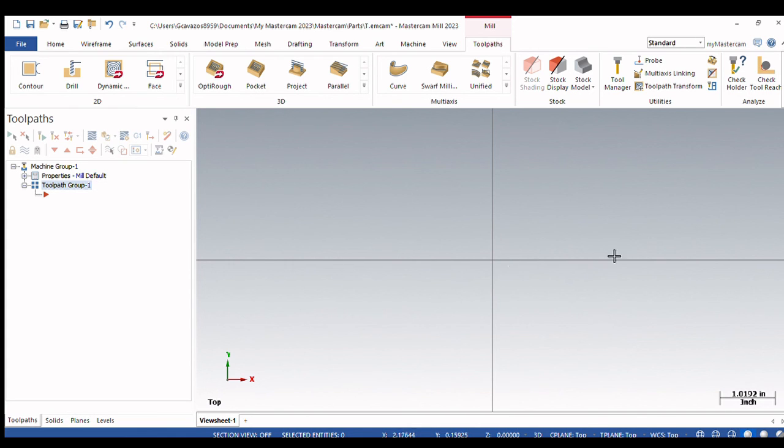So we're currently looking straight down the Z axis. This is X positive and this is Y positive, just like our milling machine is. And we'll notice the same thing when we do the lathe projects. You could turn this function on and off. We can go back to that toolbar and do it, but the other possibility, which I tend to like, is turning it off with the F9 button. So if I hit F9, that should go away.